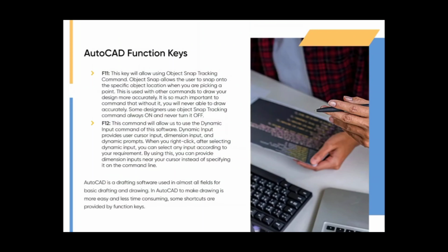F12, this command will allow us to use the dynamic input command of this software. Dynamic input provides user cursor input, dimension input, and dynamic prompts. When you right-click, after selecting dynamic input, you can select any input according to your requirement. By using this, you can provide dimension inputs near your cursor instead of specifying it on the command line.